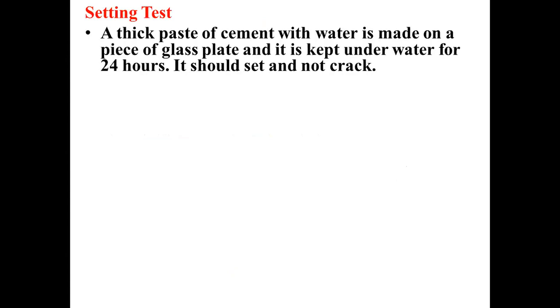For that we are going to prepare a paste with water on a piece of glass plate, and it is kept under water for 24 hours. It should set and not crack. No cracks should be visible on the paste. If cracks are visible on the paste, the cement is not of good quality.